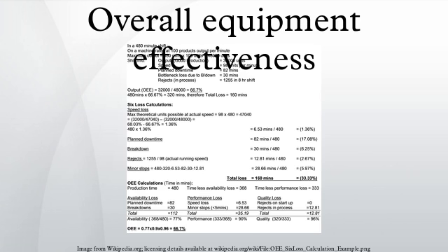Overall equipment effectiveness, OEE, breaks the performance of a manufacturing unit into 3 separate but measurable components: availability, performance, and quality. Each component points to an aspect of a process that can be targeted for improvement. OEE may be applied to any individual work center, or rolled up to department or plant levels. This tool also allows for drilling down for very specific analysis, such as a particular part number, shift, or any of several other parameters.